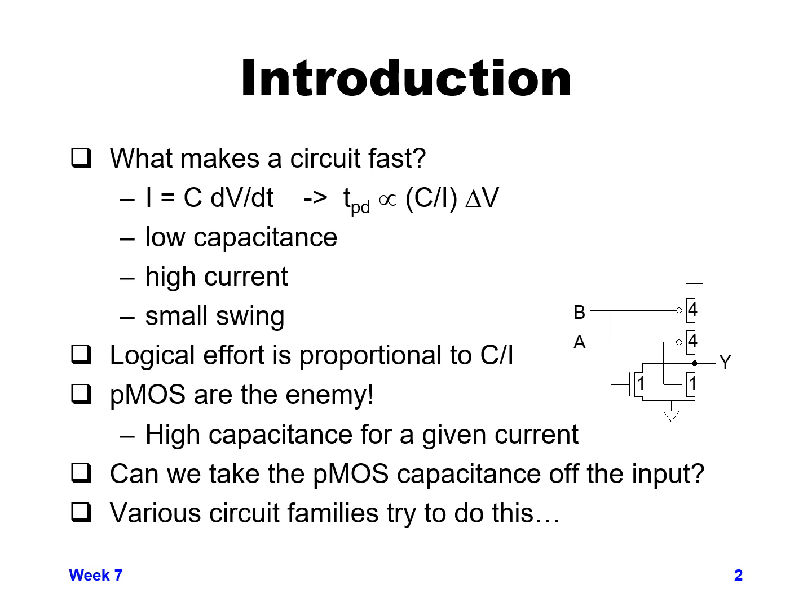And so the amount of time it takes, which is how fast a circuit switches, the dt value, is proportional to C over I times dV. So if we want to make the circuit faster, we want to lower capacitance or increase current or change the amount of voltage swing that we need. So we can decrease the VDD supply. If we can keep the current value and the capacitance value the same, a smaller voltage swing will cause the time delay to be faster.